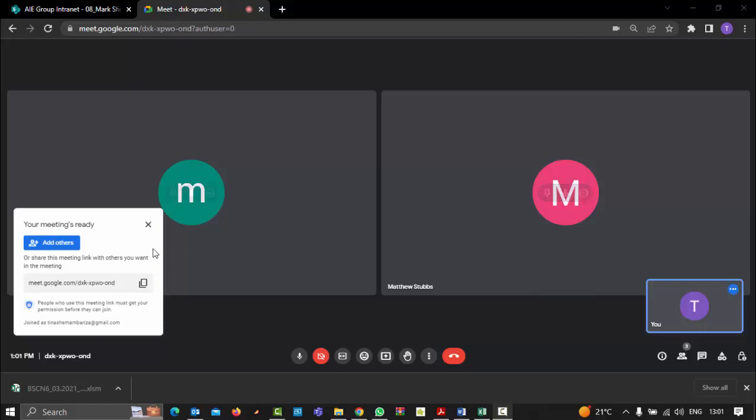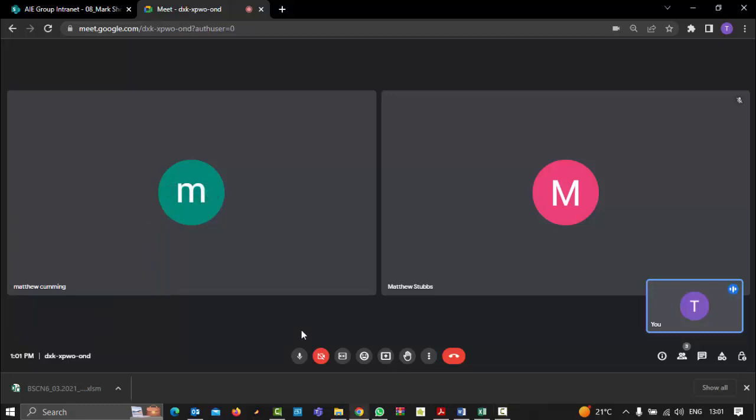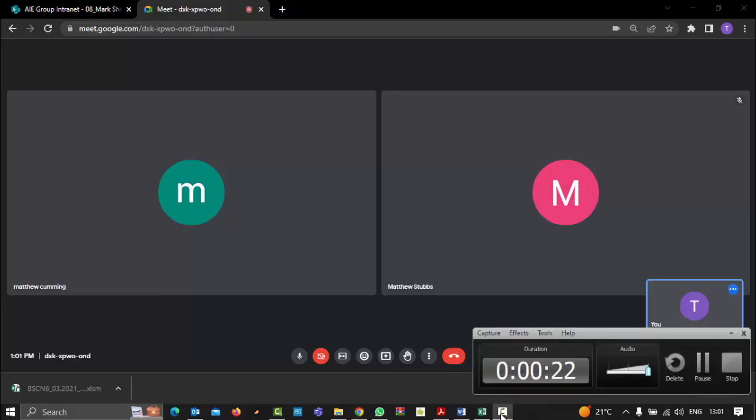proper functional design. So I want you to skip that part. Then once you are done with checking clear spacing and minimum and maximum percentage area provided, you go straight to shear calculations. So that's what I want you to do.